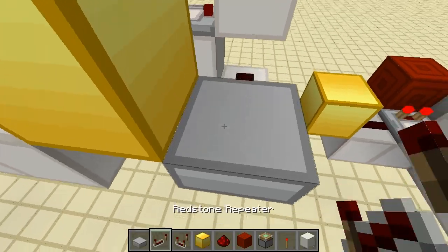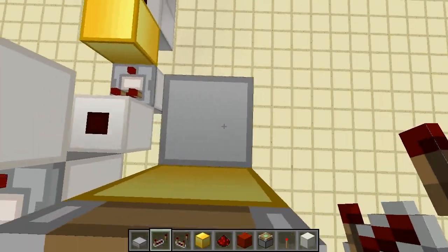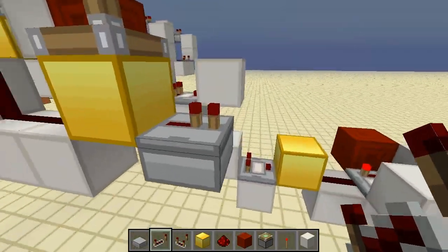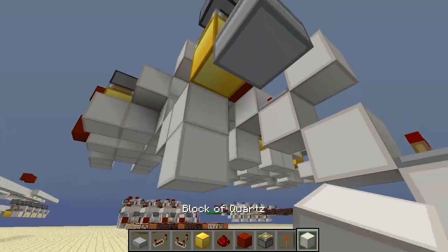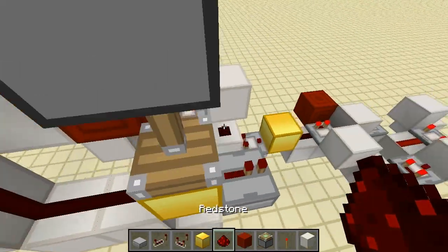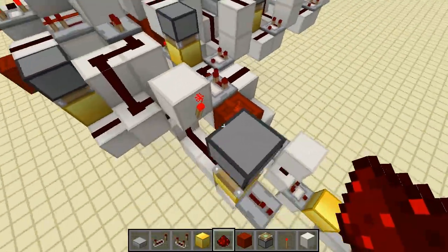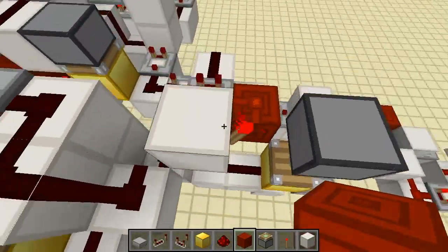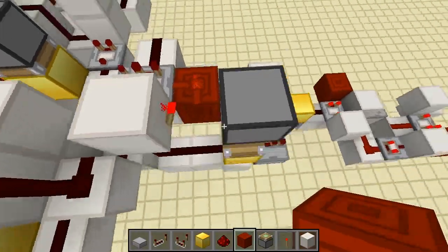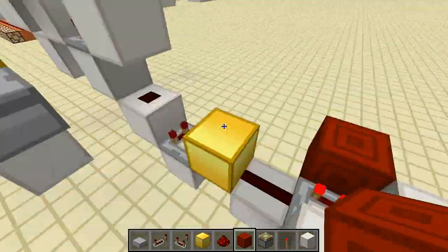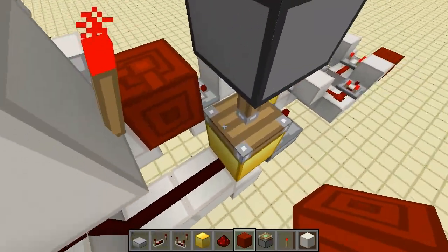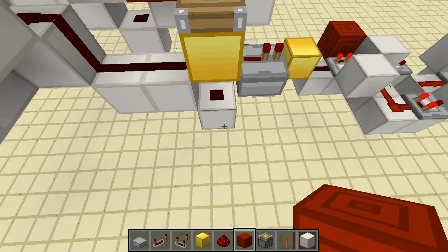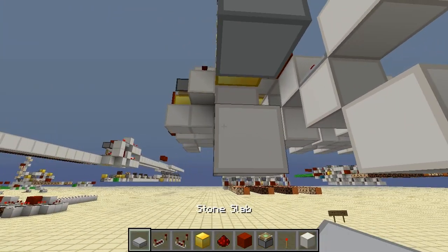It's a multiplexer rather. And by a multiplexer, what I mean is that if the piston is down, the signal will go straight on through, and if the piston is up, the signal will come down here instead. And that is handy because it allows us to branch the program. Now, if the piston is up, i.e. if this is 15, then we want a 0 put out here if we have carry in, because 15 plus 1 is 16, which is a 0 in this digit and a carry in the next. So we can wire this down here.